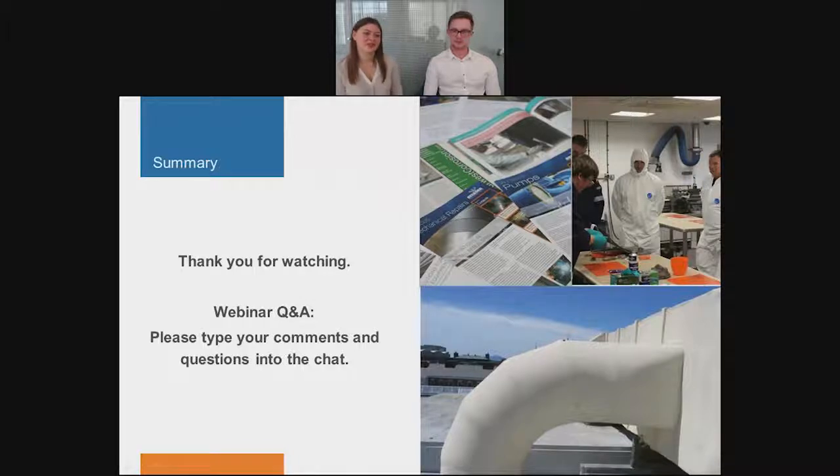The highest temperature that Belzona products can tolerate? The highest temperature product coating-wise that we have goes to about 160 Celsius, and that's Belzona 1593. Normally, that's not used in a lot of the applications we see with heat exchangers, HVAC systems. It's usually down the lower end, so we're talking less than 100 degrees. But 160 C is the highest we recommend, which is 320 Fahrenheit approximately. And that's the highest temperature for immersion circumstances.